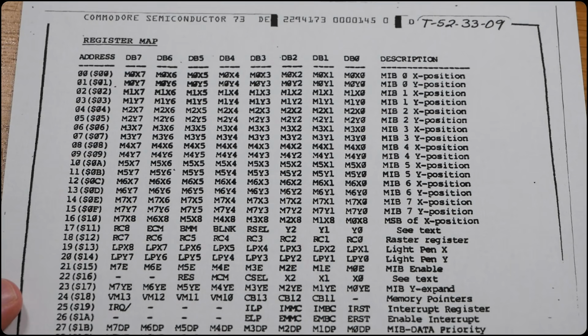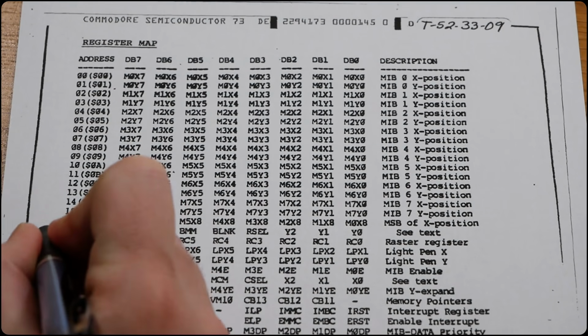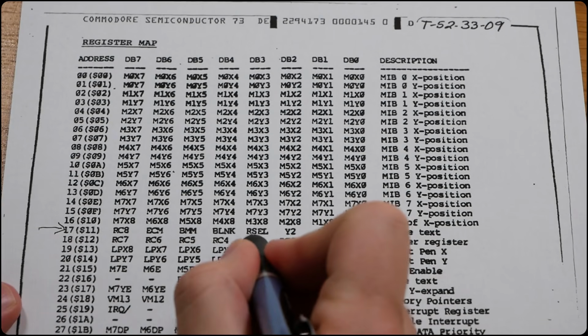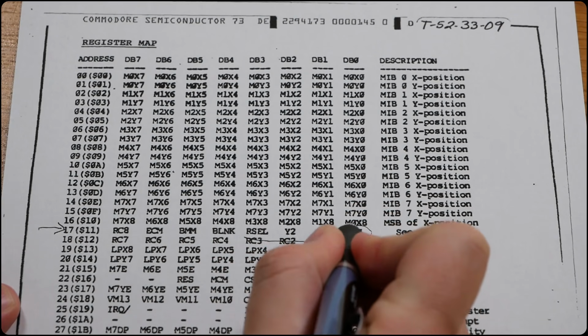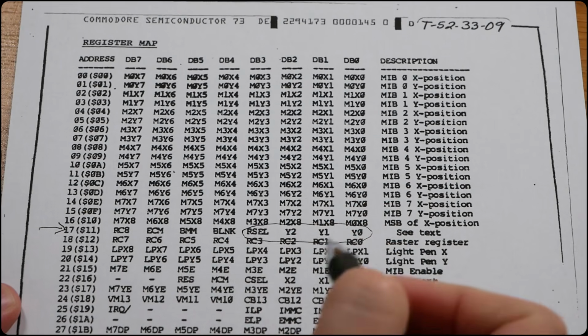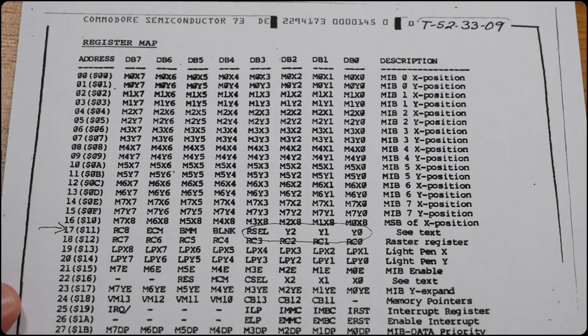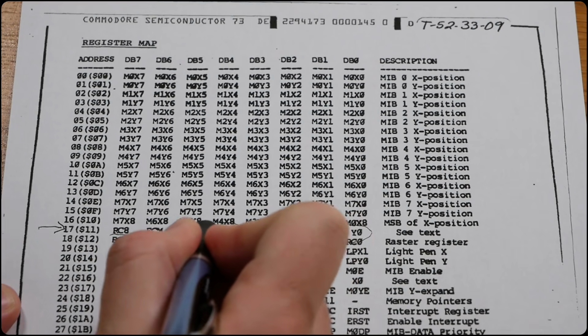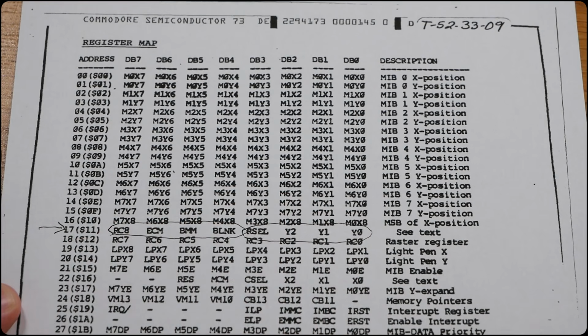And there is such a register, and it's the good old D011. Under normal circumstances, the lower bits of D011 trigger all sorts of interesting behavior in the VIC chip, but not in the vertical border area. So as long as we're up in the border, we can write anything we want to the lower bits of D011. The upper bits, on the other hand, control the current video mode, and there are so-called invalid video modes that turn the screen black.